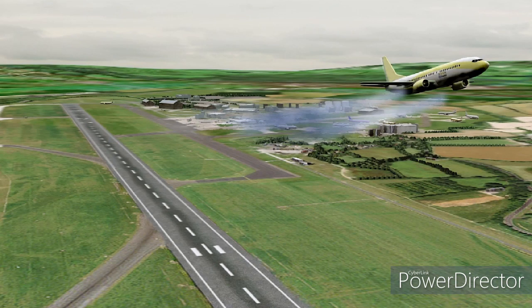If a go-around is initiated after a long stable descent with idle power set, then the engine often shows evidence of great amounts of oil being burnt and ejected with the exhaust.